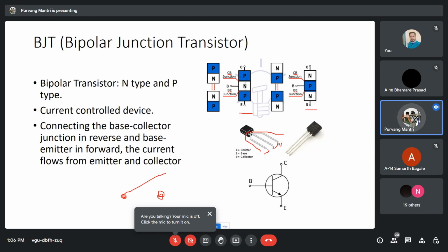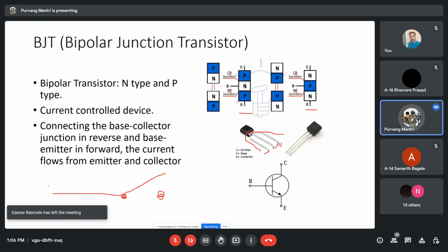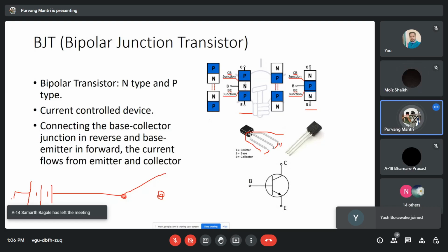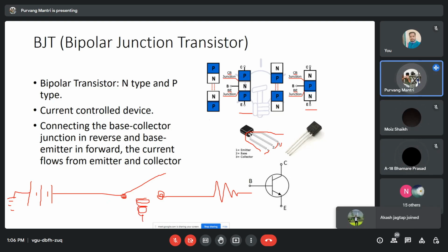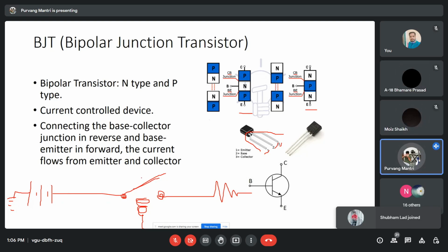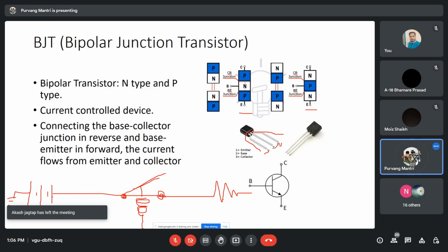Let's assume this is a metal strip. We have supply over here, and let's put a ground over here. And here is some resistance or load on the output end. We are placing a solenoid, which is controlled electronically. What happens when the solenoid gets electricity? It gets charged up, and because the strip is made of iron, it is going to get attracted towards the solenoid and close the gap, and thus allow the electricity to pass from the battery to the load.